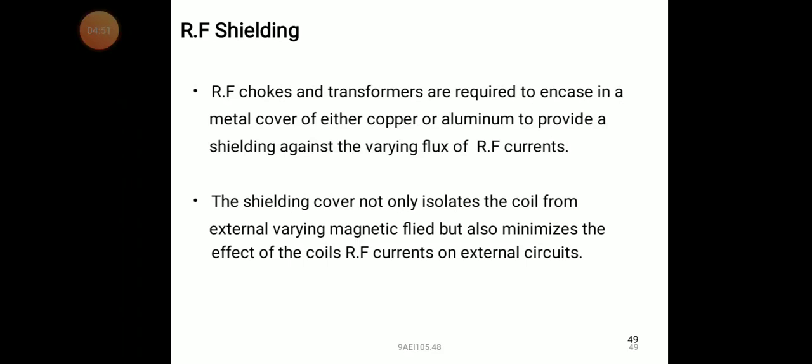The shielding cover not only isolates the coil from externally varying magnetic fields but also minimizes the effect of the coil's radio frequency currents on external circuits. That is the importance of radio frequency shielding. We need to provide shielding for the coil.